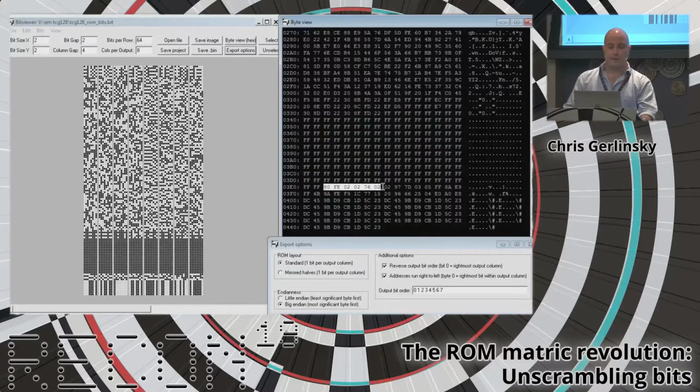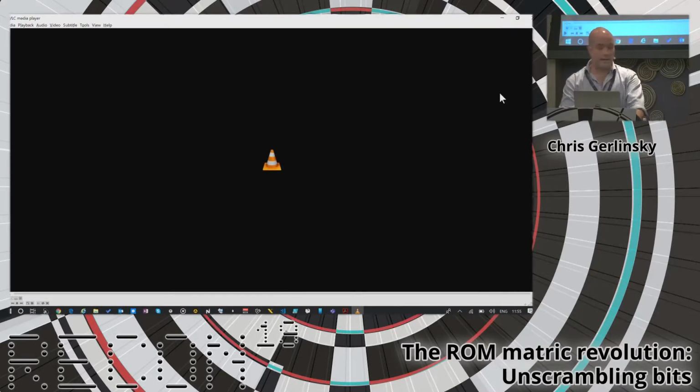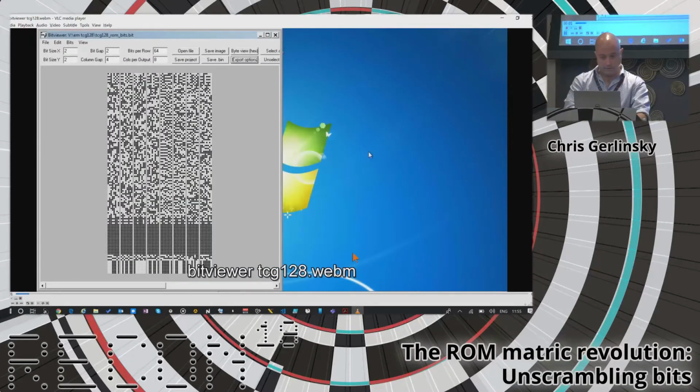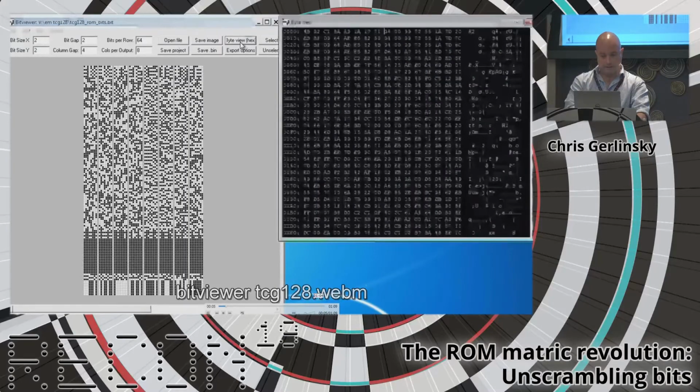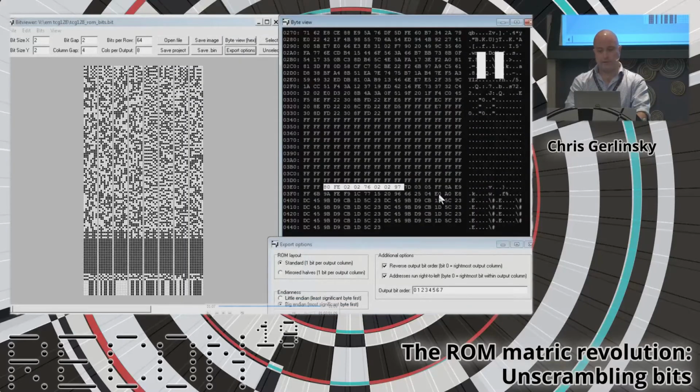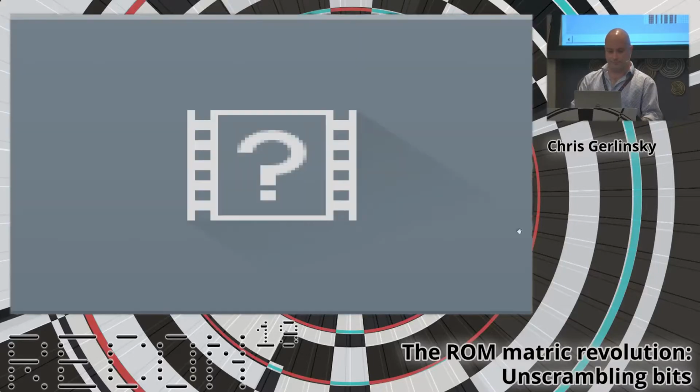And then after doing that, the next thing that I'm able to notice is there is an 8-byte sequence that appears to be plain text. That was valid 8051 code. There was an infinite loop there, which is a pretty common thing to see at the end of code blocks. The ADFE is an infinite loop, followed by some long jumps. There's sort of a vector area. So there's 8 bytes that turned out in plain text, but the rest of it still isn't valid code at this point in this chip.